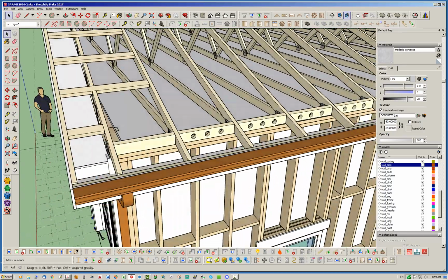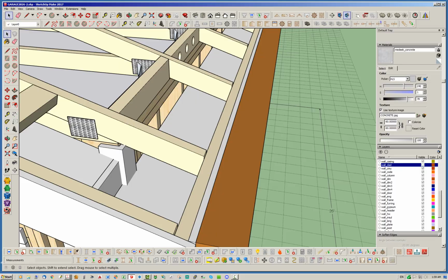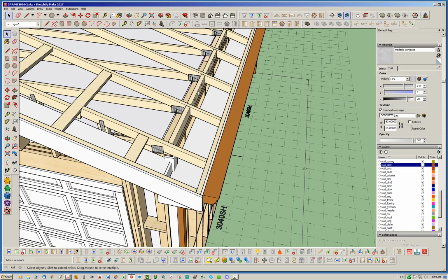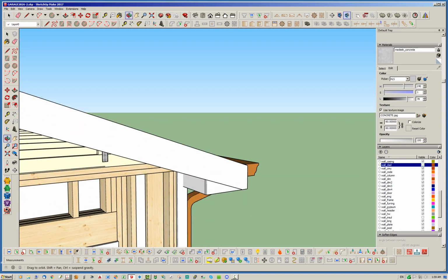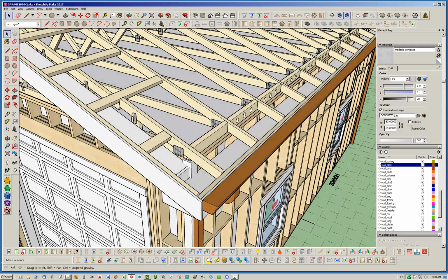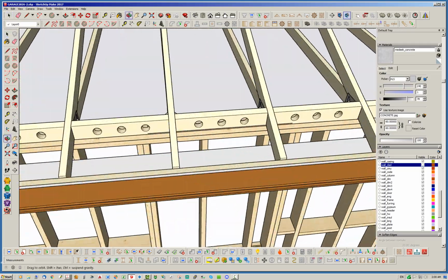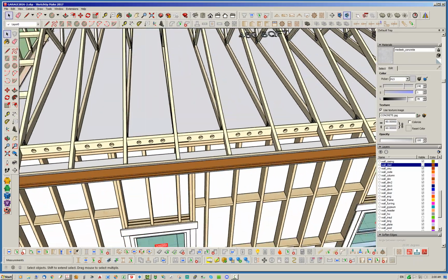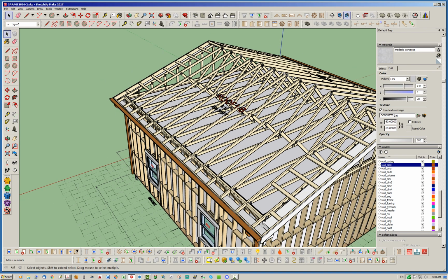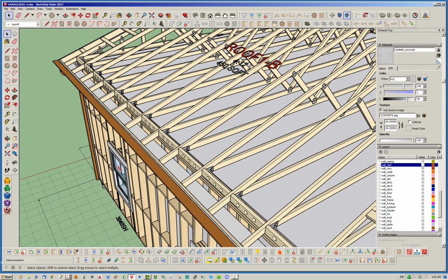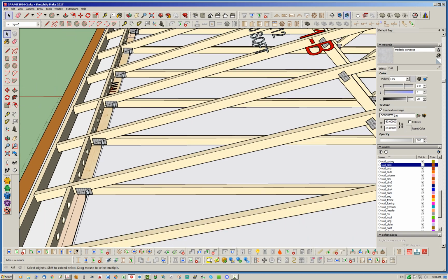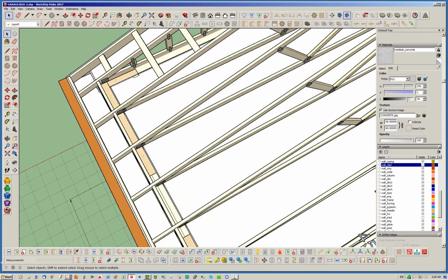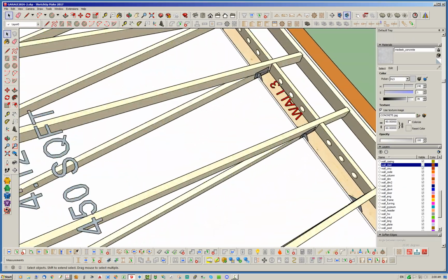Also, we have our soffit and fascia drawn, our finished soffit and fascia. We have the sub fascia here, but we also have the regular soffit and fascia all boxed out nice. And we can change how these corners are configured as well. But yeah, you've got your bird, I don't know what you call them, your bird holes. That's typically what ends up getting in those things, birds. But you got all the blocking shown, and we even have the H1 hold downs holding the rafters down. So those are all on all the rafters here. And notice on the other side, same deal.